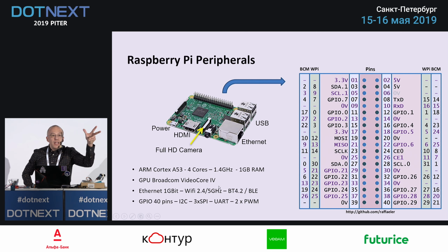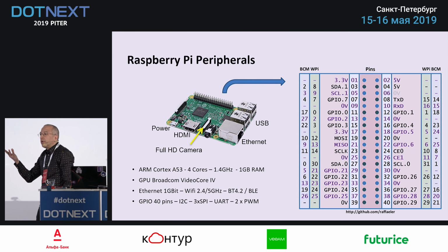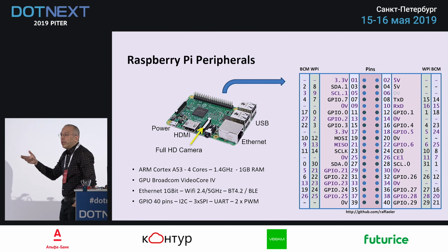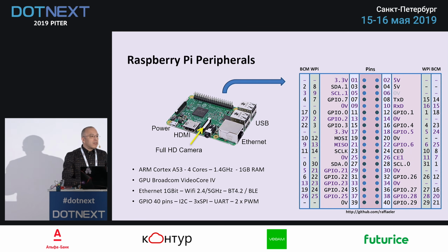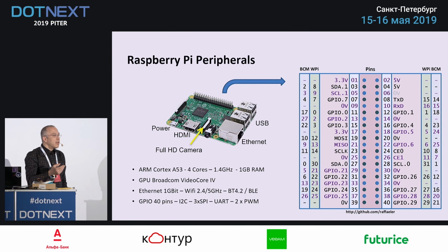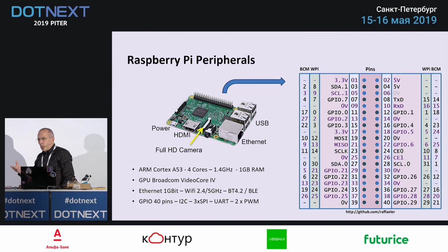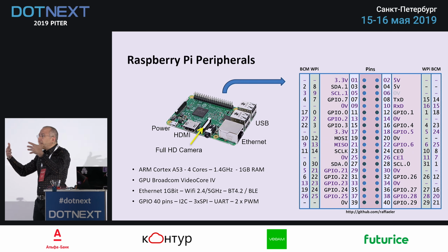Basically, you have three classes of the most important IOs that you can use. The plain pins, the GPIO, which is general purpose IO, and then the port called I2C, the inter-IC communication. It's a standard created by Philips many, many years ago to avoid parallel communication.